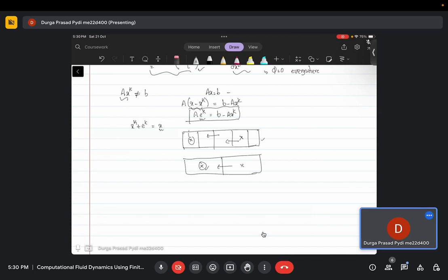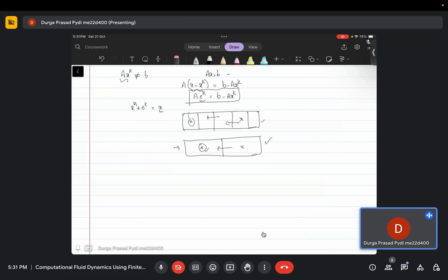But the problem with a coarser mesh is that sometimes it might give you non-physical results. Like we have seen previously in convection diffusion cases, and even in unsteady problems, delta t and delta x are related. So for a given delta t, you cannot arbitrarily take any delta x. Because of these limitations, there will always be some limit on how coarse you can go. So you should not actually be solving for this original equation.